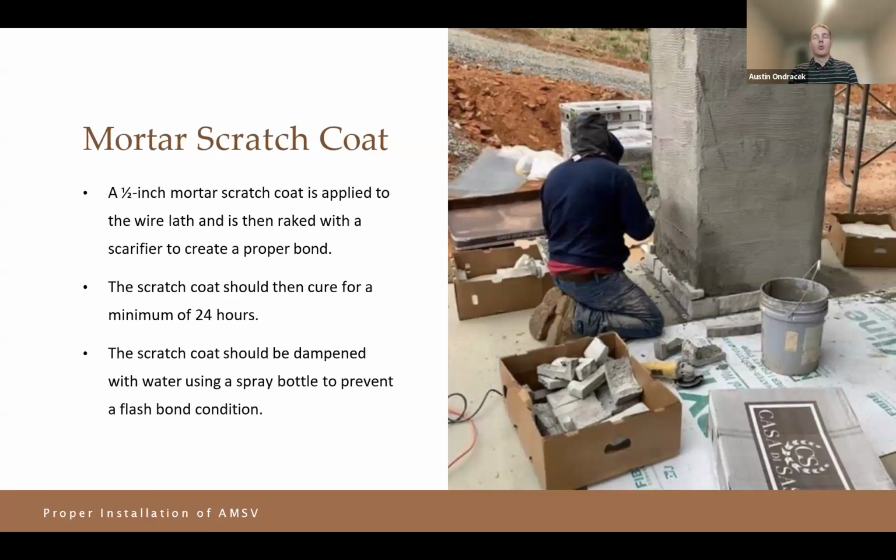Talking about a mortar scratch coat, the biggest thing about why a scratch coat is applied is it is acting as that extra anchor. So when I think about the claw marks, in my analogy, if there's a smooth surface, pretty hard to really grip anything. As soon as you have a scratch coat, there's more grippage, there's just more area to work with for texturing and having resistance or a greater slip coefficient in that sense.